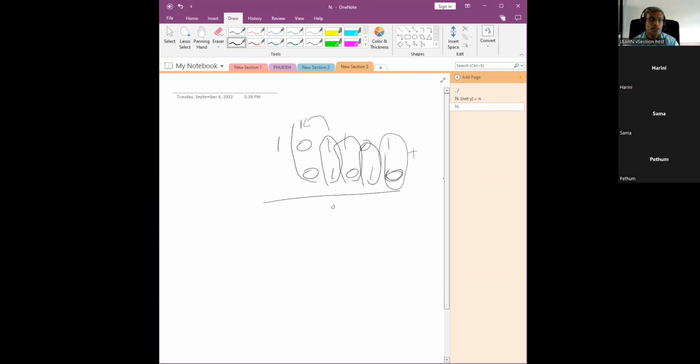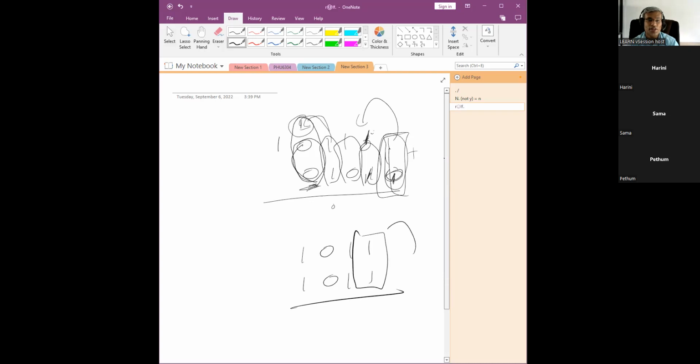So now you are adding actually 3 numbers, 2 from the original and 1 taken from the previous value. In this case, it happened at this particular location, but we don't know when it will happen. For example, if you had 1 1 here or 1 1 here, then 1 will be carried into this location. So the only place we can say for sure there won't be a carry is the last bit. If you have something like this, you can see the last bit doesn't have any carry bit coming from here. So that one you can use a half adder.